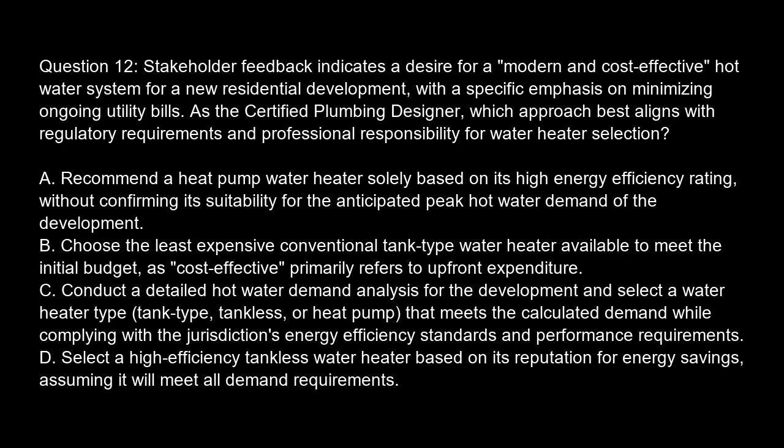Option A. Recommend a heat pump water heater solely based on its high energy efficiency rating, without confirming its suitability for the anticipated peak hot water demand of the development. Option B. Choose the least expensive conventional tank-type water heater available to meet the initial budget, as cost-effective primarily refers to upfront expenditure.